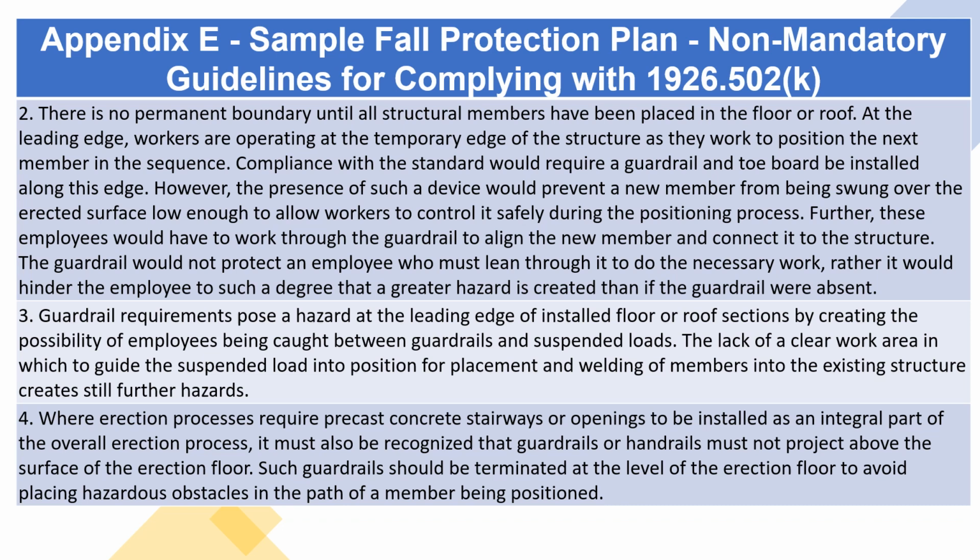3. Guardrail requirements pose a hazard at the leading edge of installed floor or roof sections by creating the possibility of employees being caught between guardrails and suspended loads. The lack of a clear work area in which to guide the suspended load into position for placement and welding of members into the existing structure creates still further hazards.